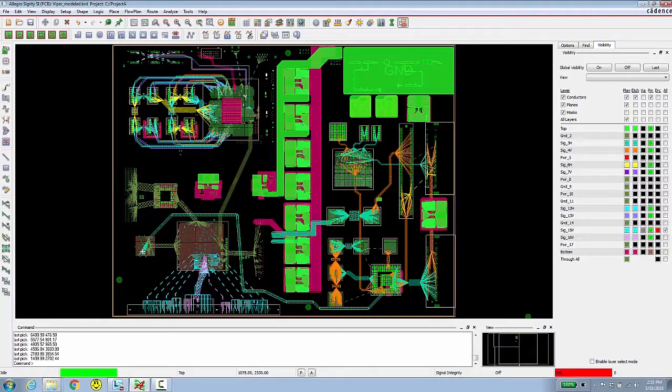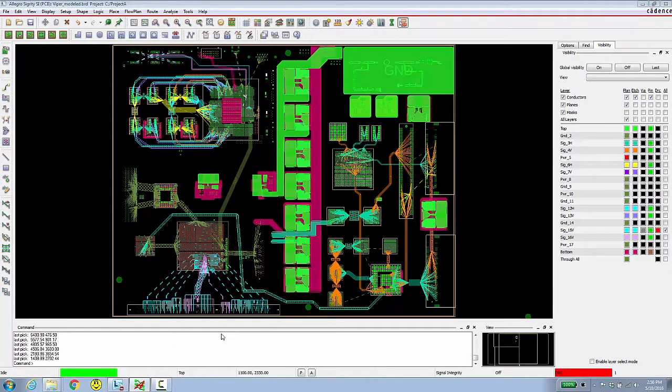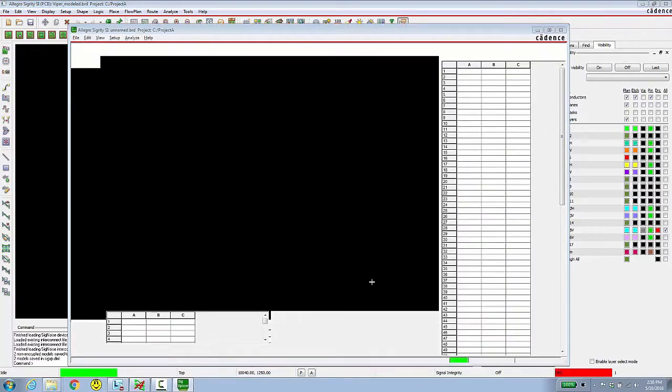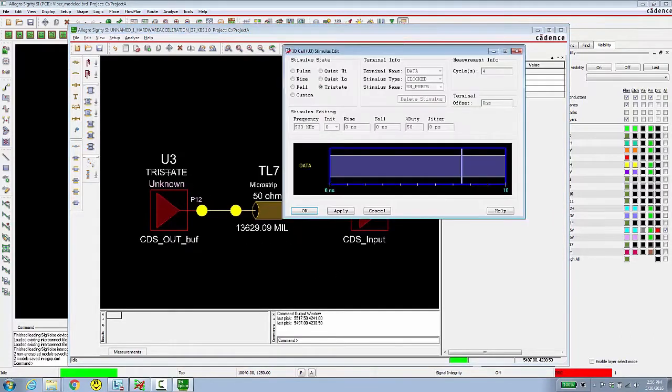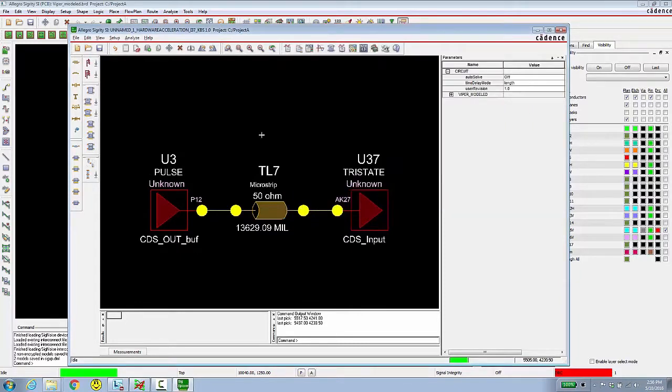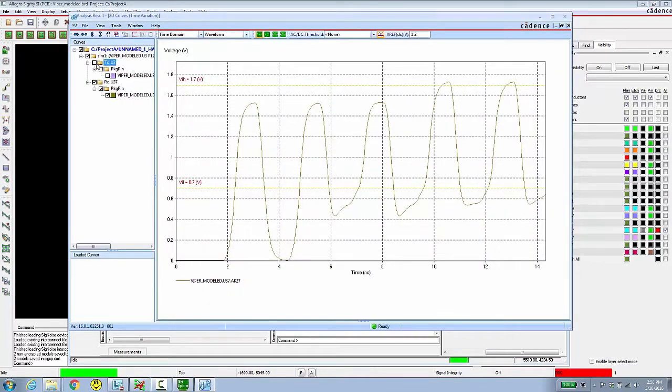If I extract one of the nets of the bundle to Signal Explorer, we will see a single T-line model representing the net. We've increased the length by more than 3 inches. Is this okay? We can go back and simulate in the design, or we can just as easily simulate here. Now would be a good time to see if we need a stronger driver to handle the length and loading. Even worse would be if this problem was not evident with the original 10-inch Manhattan distance.